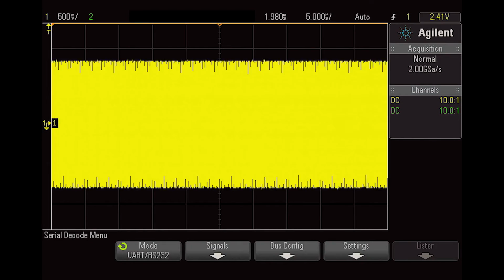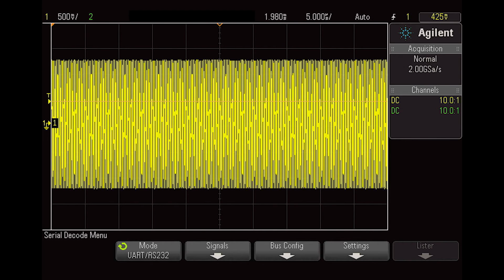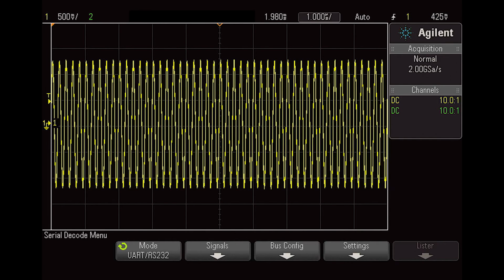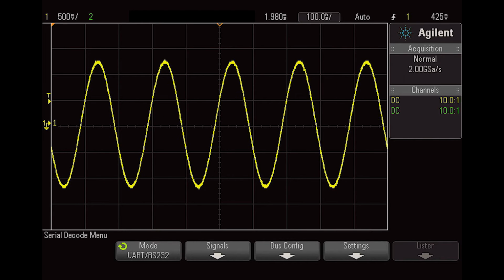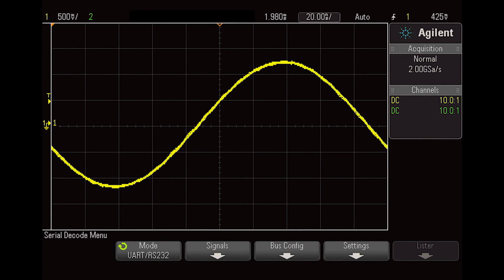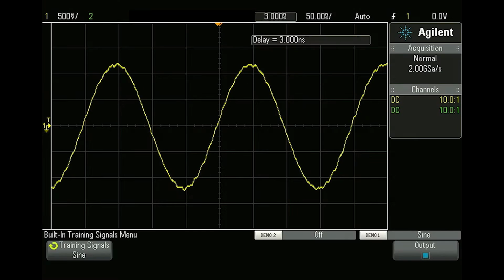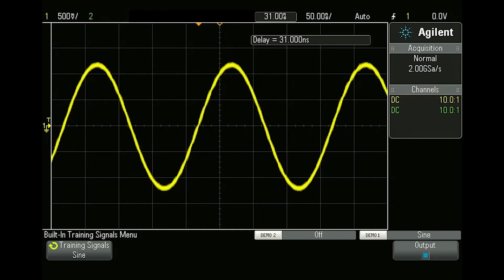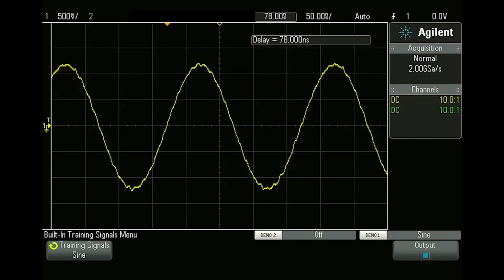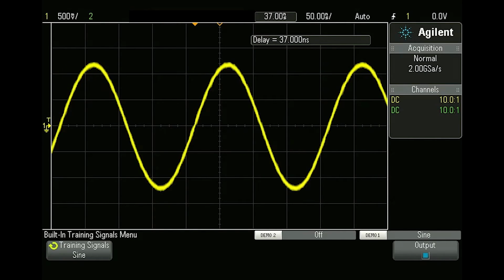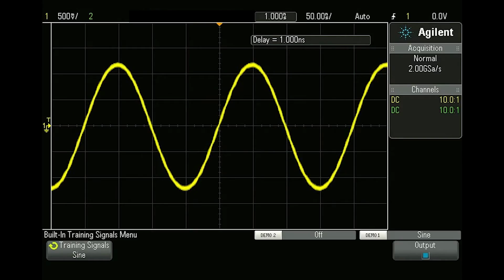The horizontal adjustment dial changes the time range per horizontal division for the display. Again, this is used to zoom in on the signal until it can be clearly seen. The horizontal position dial adds a delay into the signal so that it moves left and right along the horizontal scale. This can be used when comparing two signals so that they can be aligned.